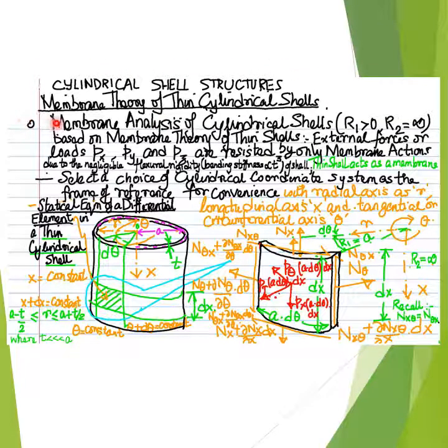However, one may recapitulate that the simplifying assumption of thin shells, that is, the simplifying idealization that the shell is thin, reduces the number of unknown internal actions from 10 to only 3 upon the application of the 6 statical equilibrium equations.